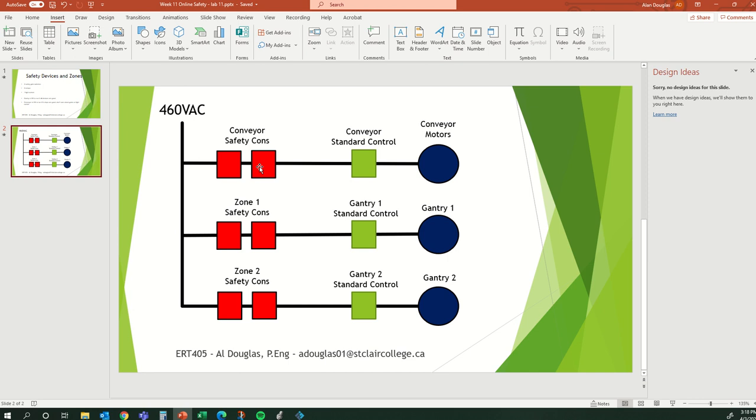So we would be shutting down the conveyors and gantries by 2 different methods if this was a true safety application. We can't really demonstrate that in Factory I/O, so we are basically going through the motions of setting up devices that would control those safety contactors, but it's really just the software that is stopping it.